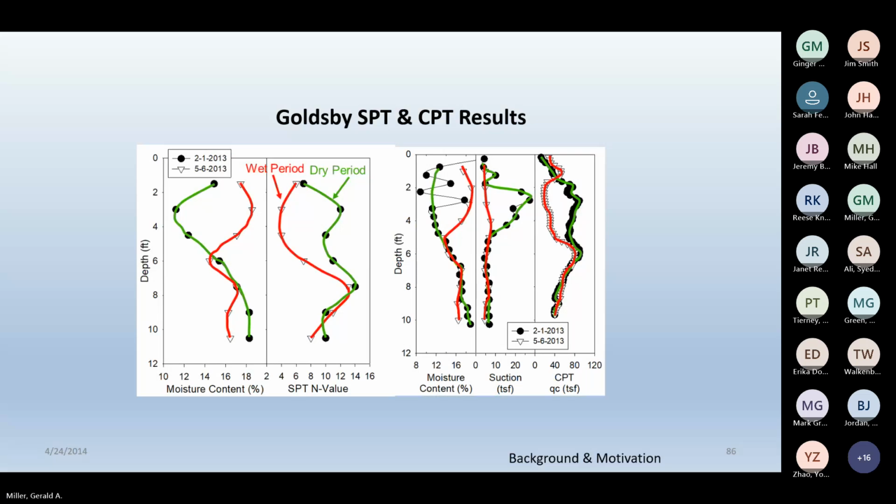What got us thinking about it was clearly the moisture contents impact our in situ test results because it's affecting the properties of the soil. So that probably translates to the fact that it's going to impact other properties like shear wave velocity or small strain shear modulus, which shear wave velocity depends on.